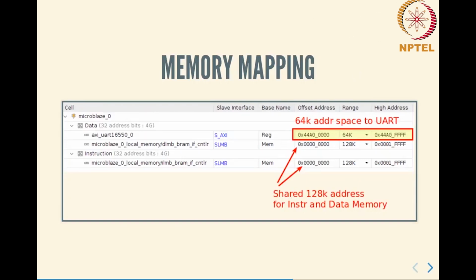And by interpreting the address and the read or write instruction appropriately, the UART can respond in any way that it likes. This means that the UART at one level is acting like a memory. The processor just needs to read or write a certain memory location in order to communicate with the UART. But rather than a dumb memory block that only takes care of storing information and retrieving it, the UART can actually process it and return information that is enhanced in some way.